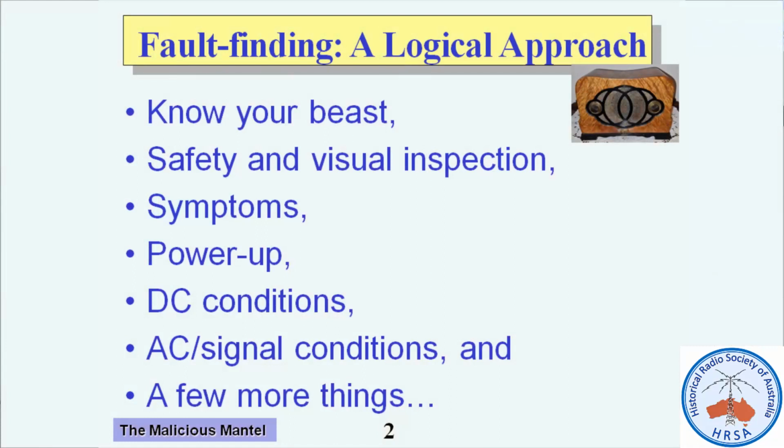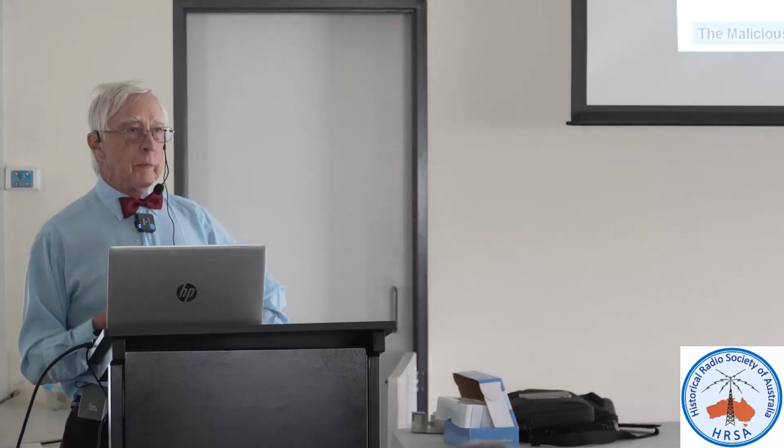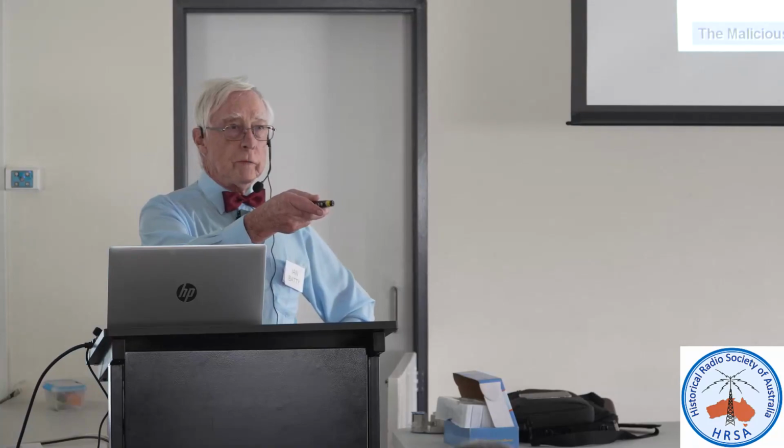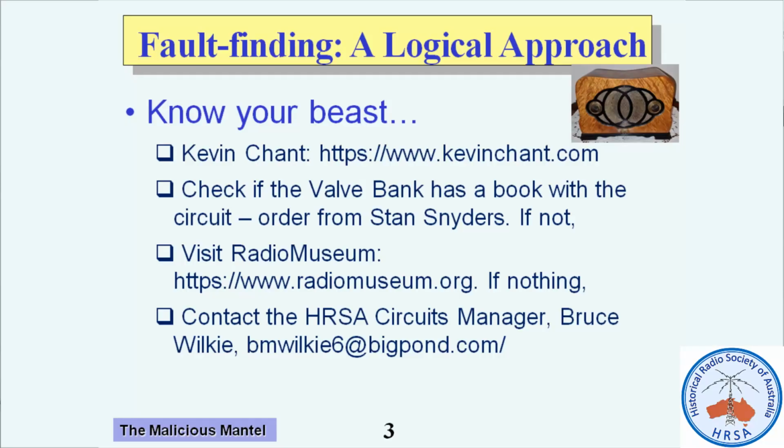I reckon, here's the process. Know your beast, safety and visual inspection, symptoms, power up, DC conditions, AC and signal conditions, and there's just a few more things. You can get information, and thank you to Kevin Chant for his excellent website. If you do pop onto Kevin's website, please send him a thank you email, because the amount of work he's done is just completely outstanding.